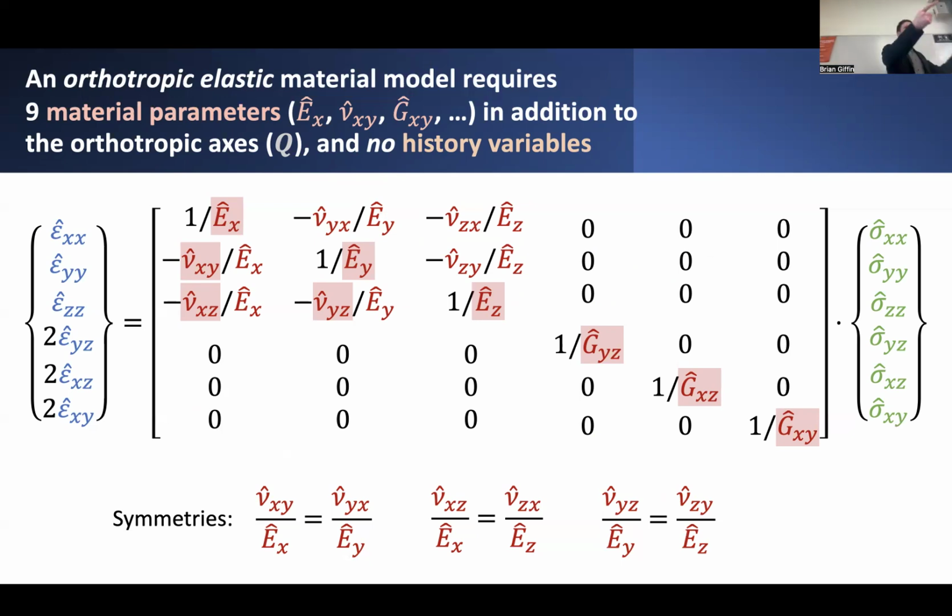And you can also measure, under these different modes of uniaxial extension, the resulting apparent contraction strain in each of the lateral directions under a given axial loading direction. And that's how you come up with these different values of the Poisson's ratio measured relative to a given loading direction. So you come up with all these different parameters.